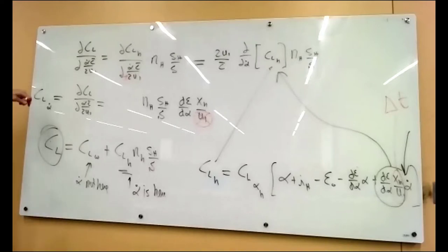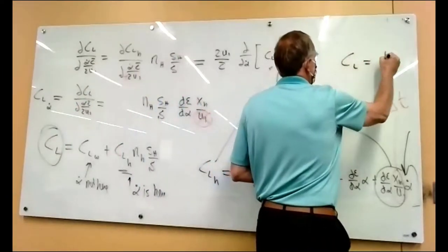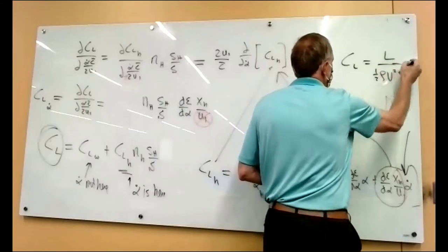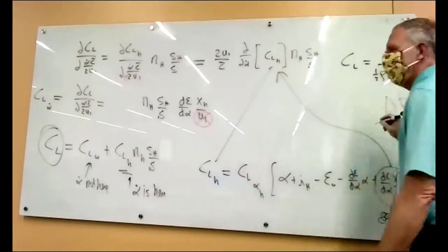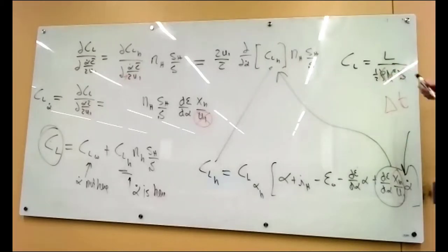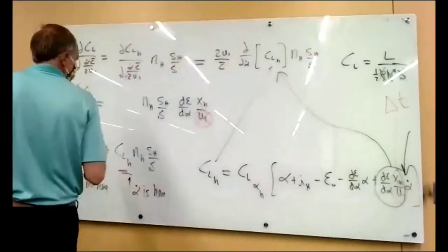So this non-dimensionalization is similar to why we define CL as lift over 1/2 rho V squared S, because it takes out the velocity dependence. It also takes out the dependence on density and area of the lift. So you don't have to recalculate or relook up your lift every time you're flying at a different velocity. Same deal here. So we do get that term knocked out.